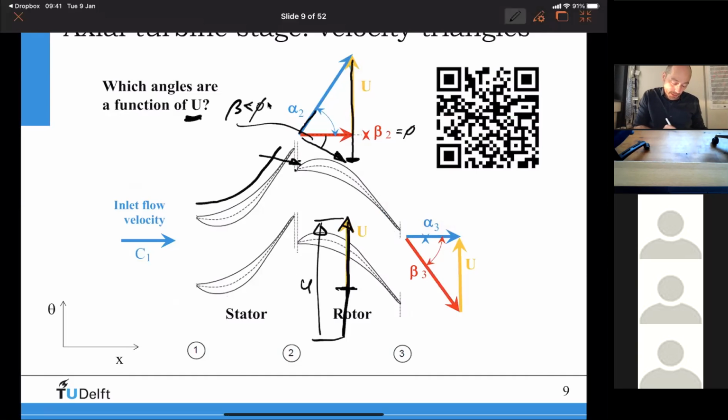And this thing is called the suction side. This is the suction side, and this is the pressure side. So the flow will hit the suction side here. And then if you think of a flow that would probably do something like that, you will see that you will get separations here, right? You will get separations on the pressure side if you increase the rotational speed, if you have losses, of course, and if you have viscosity in the flow. But anyway, afterwards, you can say, okay, the flow will have flow separation here, maybe, since the flow comes this way, then you will have flow separation here.